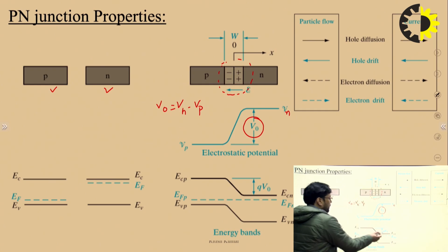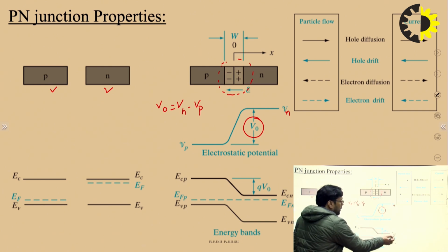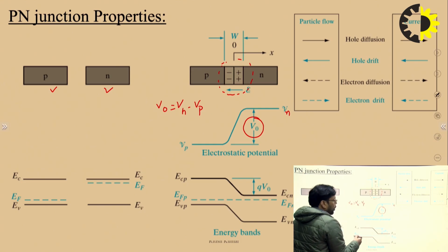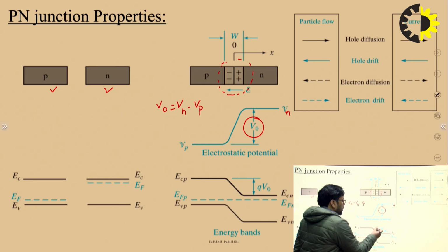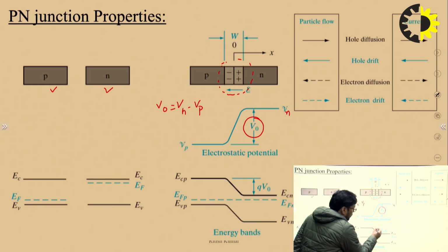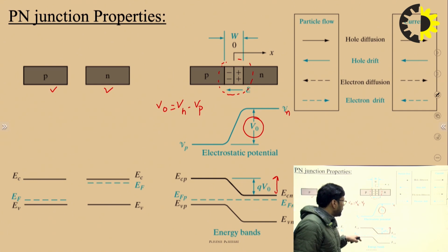You can see here, while making the PN junction, we have a single Fermi level, or an aligned Fermi level, between the p-type and n-type semiconductor, and due to the difference in the doping level, we have a contact potential. This is the contact potential level, and this height is also known as the barrier height, right? This is the aligned Fermi level throughout the PN junction diode.